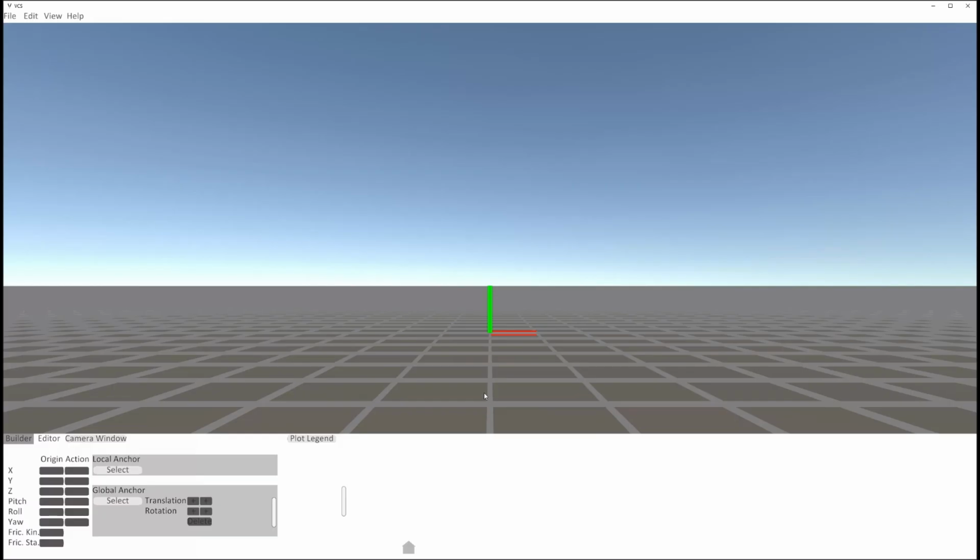Before you get started with the program, you'll need to set a few properties in the properties window, including gravity, property unit, which is the precision for properties, length unit, which is how much distance is between each calculated unit, R1 angle, R1 offset, which sets the force track offset, R2 angle, and R2 offset, which sets the track 2 properties.